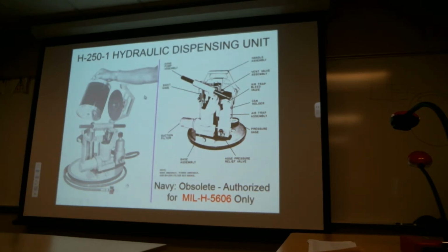The bottom of the can then serves as the entry point for hydraulic fluid that you can use with a hand pump to service the reservoir. The pierce at the top works as a vent opening for the can itself. And by intent, it pierces both ends of the can, so it prevents you from reusing the can for any other purpose.